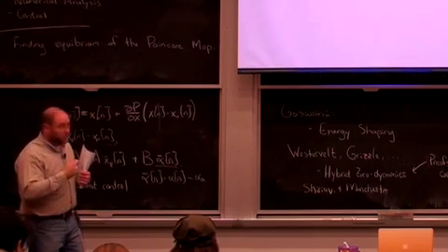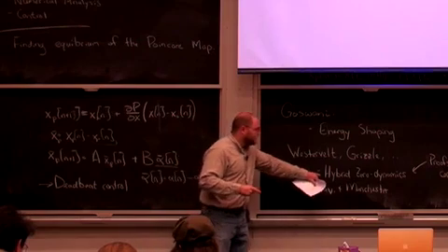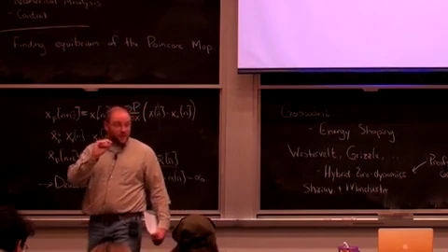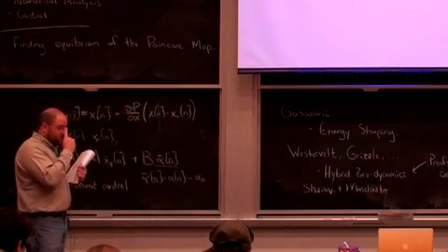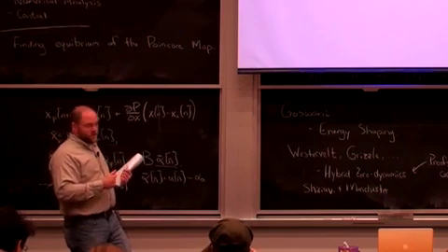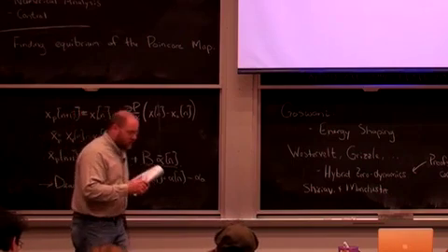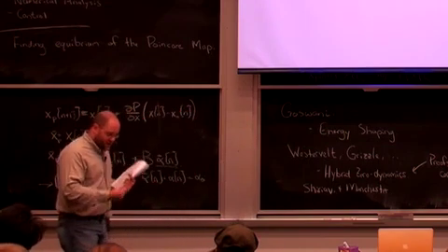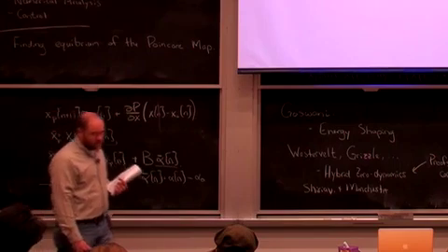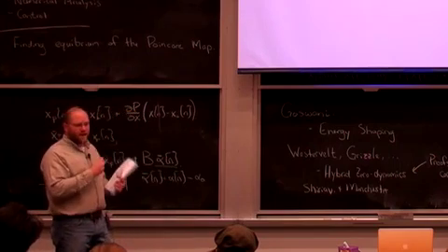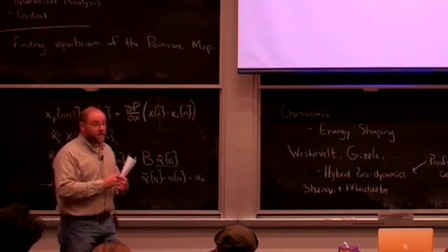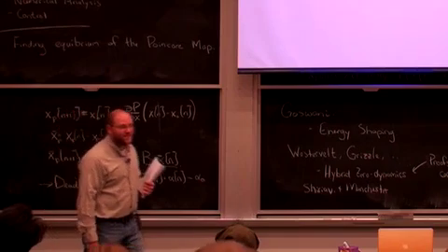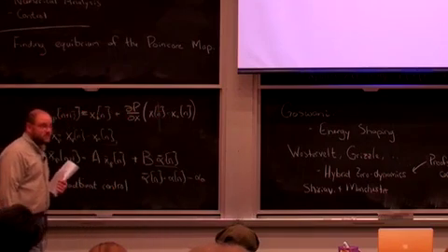Okay? So the results that these guys on the hybrid zero dynamics, they talk about the zero dynamics of the resulting output dynamics that you drive to zero. When your PFL controller has done its job, and it doesn't have to be a PFL controller, it could be a PD controller, when you've driven all your actuated joints to the desired trajectory, if you parameterize that trajectory off, let's say, the ankle angle, then your whole big complicated bipedal robot, 5-link, 10-link, whatever, looks like a rimless wheel rolling around the stance foot. And that's a beautiful idea.